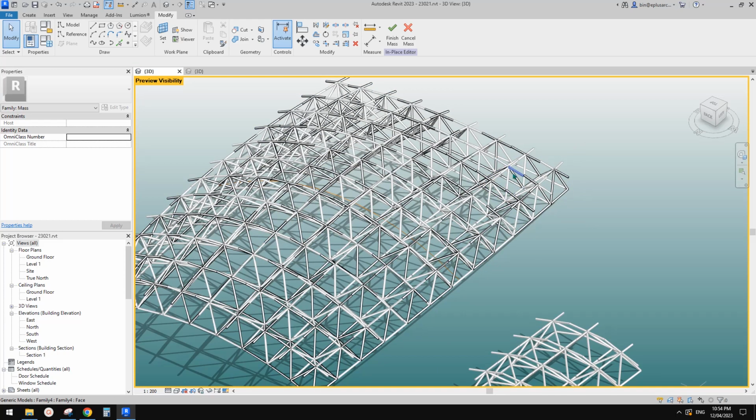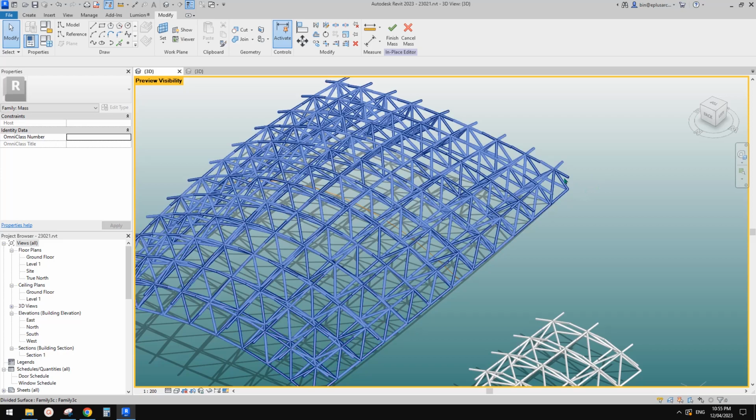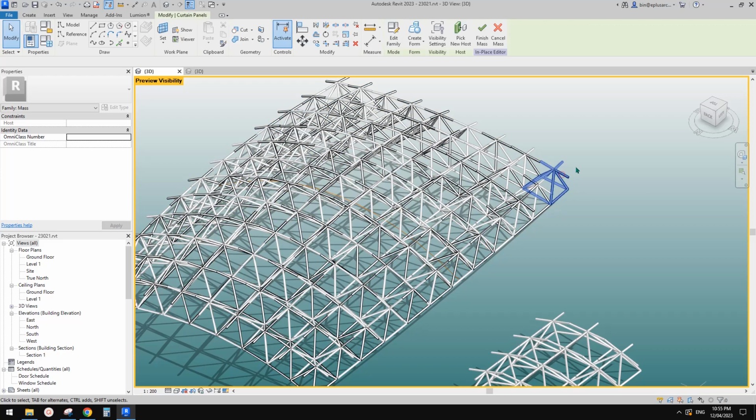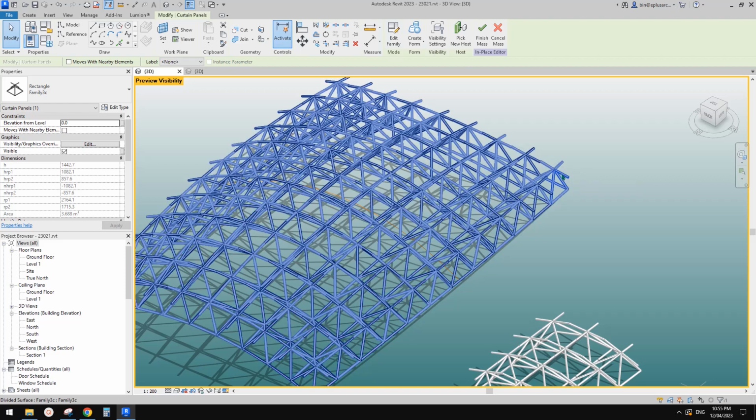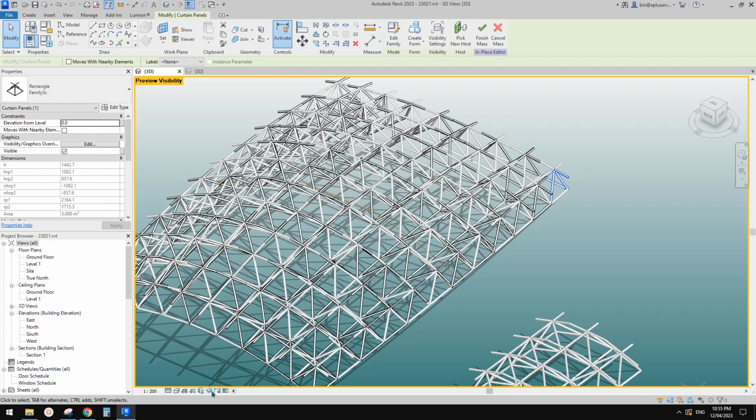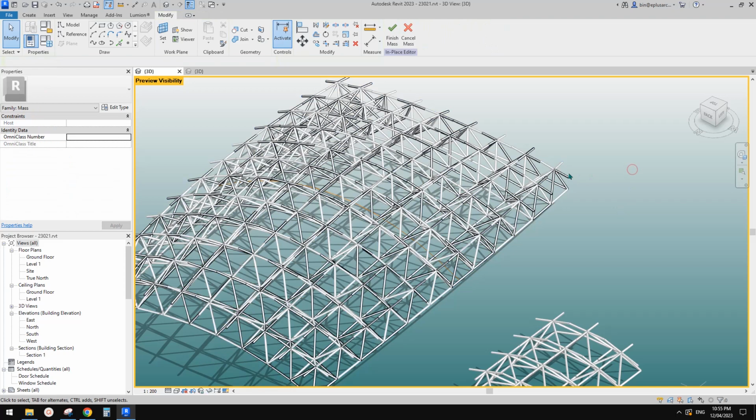tab through all these individual adaptive families or shared families. So what you can do is select one of these. Okay, so here I have one of the pattern-based families selected in the type IC, which is isolate by category. If you click on this one, there's an option of isolate category, which is the shortcut IC.